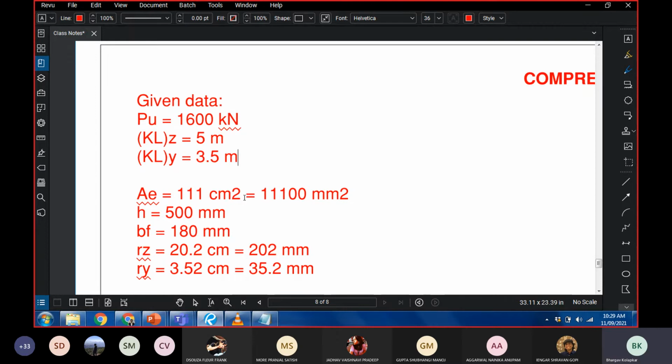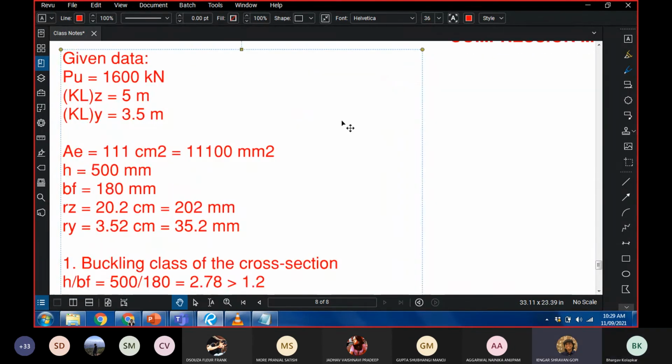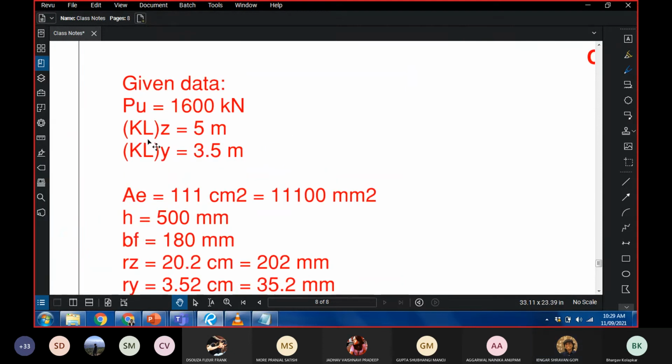Can someone answer this question? Is it because the load is not directly acting in a vertical fashion, but there's also an angular component? That has got to do nothing with effective length. Effective length is a function of end constraints only and only.